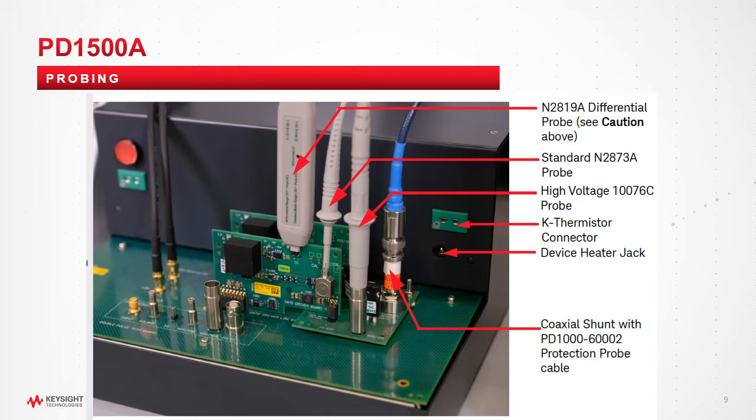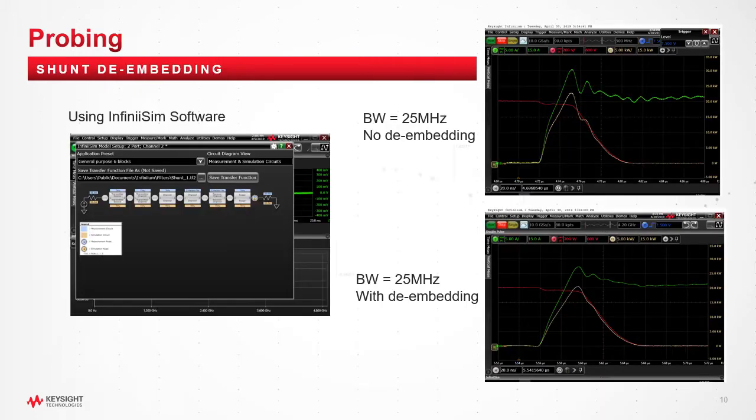And of course it's also very important that you de-embed all of this. Here we use the Infiniium software running on our instruments, and you see on the right-hand side an example of no de-embedding versus de-embedding. This is also done for the skews and other effects introduced by the measurement equipment. By characterizing our probes and putting the S-parameters into the de-embed function, you can get to the real measurement point and the curves you want to see.